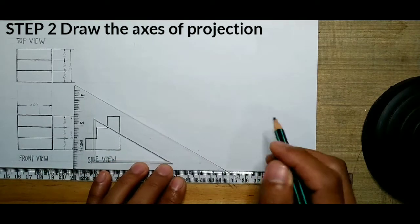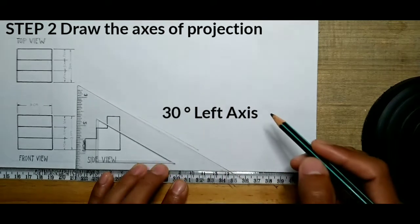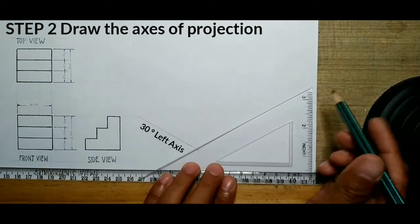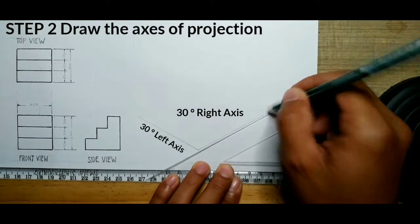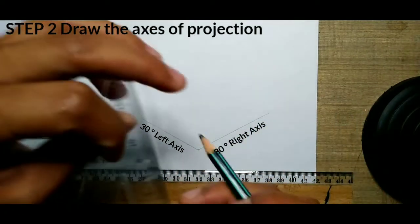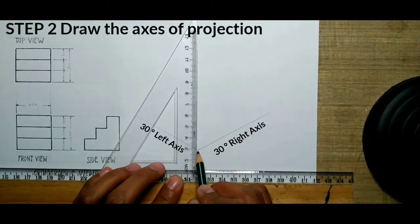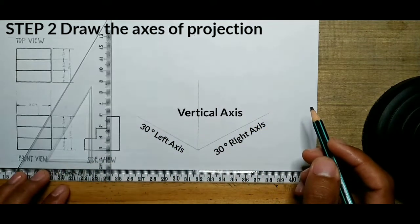So first, 30 degrees left, 30 degrees right using 30 by 60 triangle. And the third axis is the vertical axis.